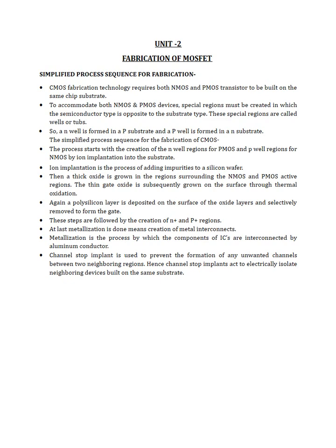Till now, we have already seen the individual fabrication steps in integrated circuits. Now we will see how these steps are used one by one to make N or P-type transistors and ultimately a CMOS fabrication, how it can be done. So actually we need to accommodate both N and P-type devices onto the same substrate to make a CMOS.